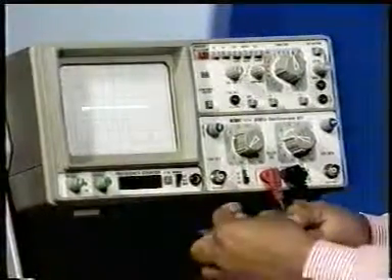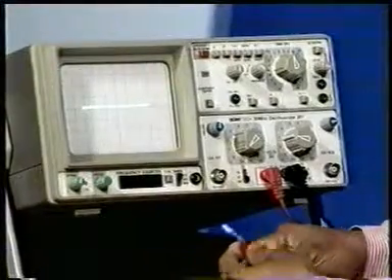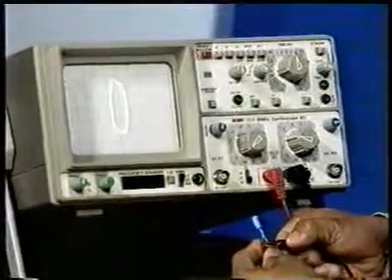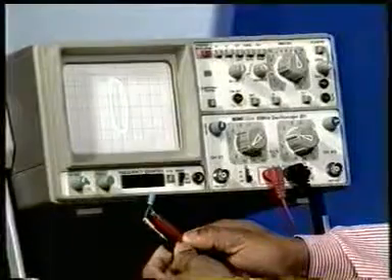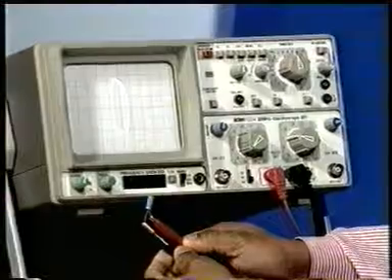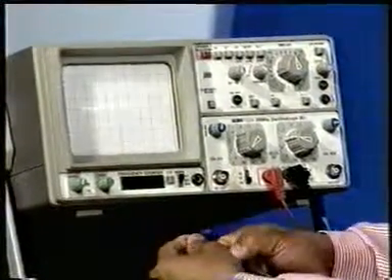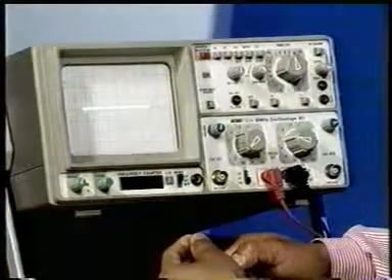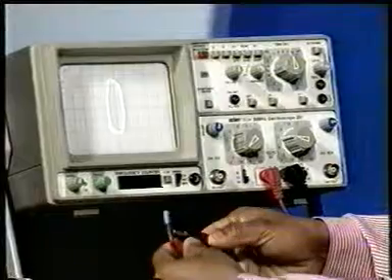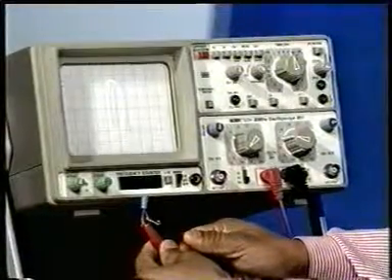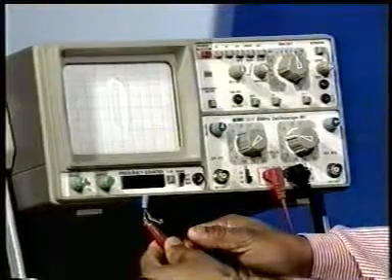Now a capacitor, it is a dielectric capacitor, and he is connecting it between the two leads. A loop is coming. This is the loop which shows that the capacitor is healthy in nature. You can reverse the polarities. Yes, again the same loop is being seen. So it confirms that the capacitor is healthy in nature. Fine.